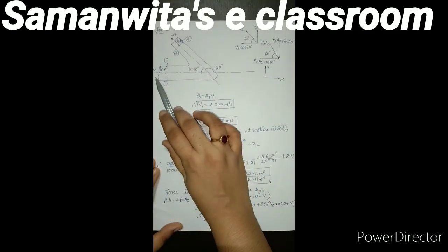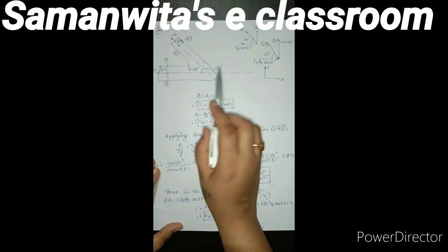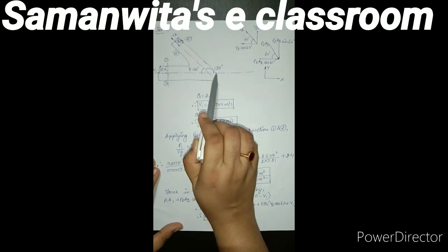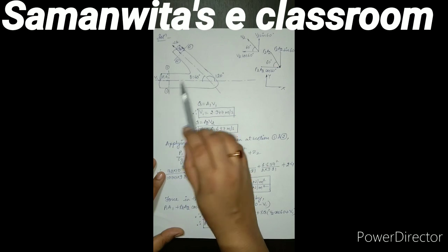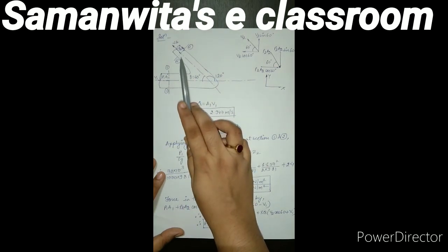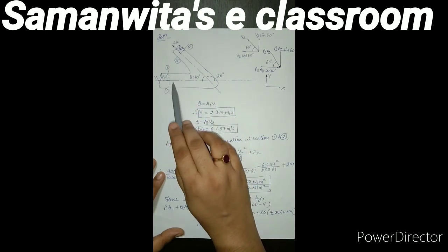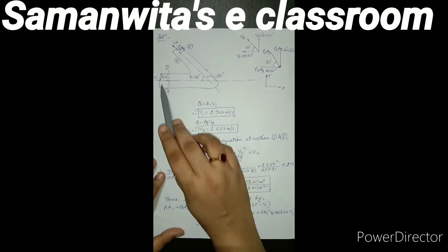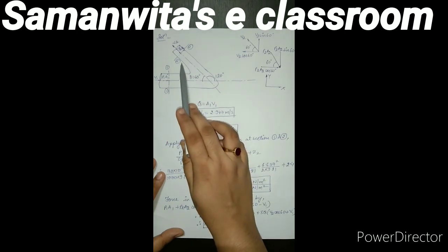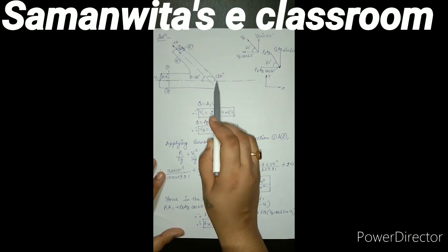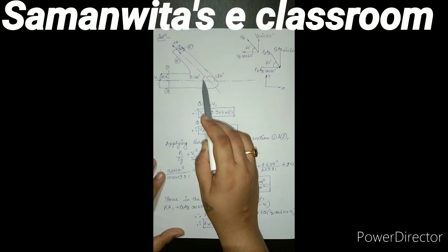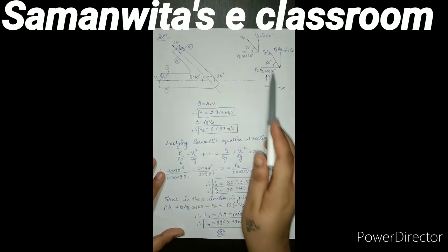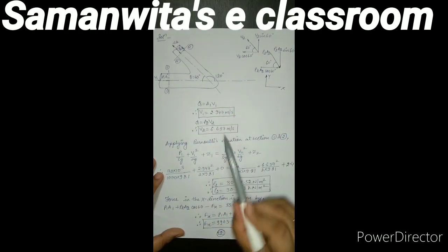I'll first start by drawing the figure. I draw a horizontal axis and I draw the angle of 120 degree. Here the diameter is 360 mm, and here, at this section the diameter is 240 mm. The water is entering with velocity V1 and leaving with the velocity V2. At the section 1, the pressure force is P1A1. At the section 2, the pressure force is going to be P2A2. Since this angle is 120 degree and the total angle is always 180, so this angle becomes 60 degree. I am going to resolve V2 and P2 like I have done in the previous numericals.